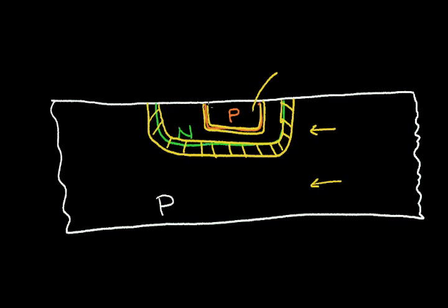And I can know that this depletion region between the p and the n material here, this is a thinner region. And it's thinner because the concentrations are higher. So I could just look at this structure and I know that the capacitance per unit area for this depletion region is small. And the capacitance per unit area of this depletion region is higher.